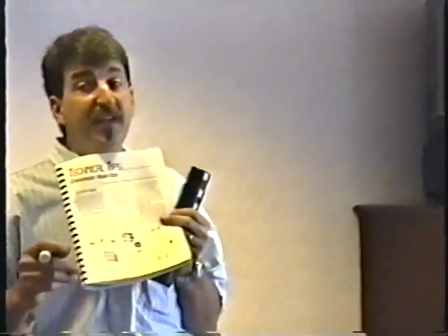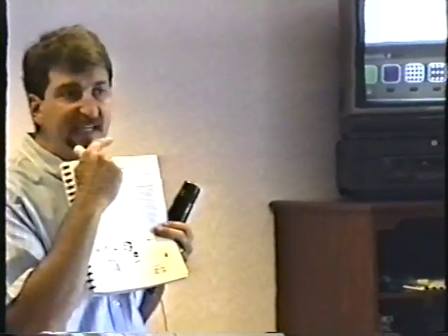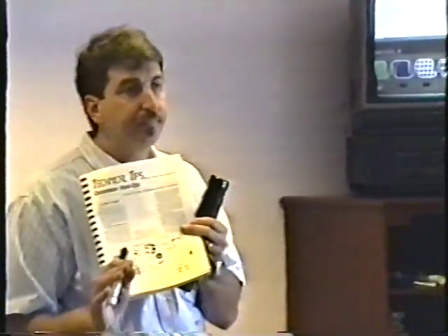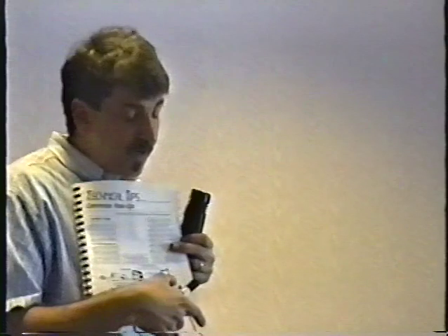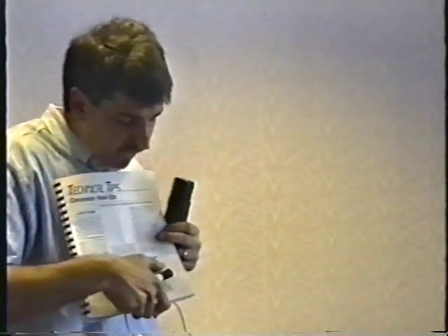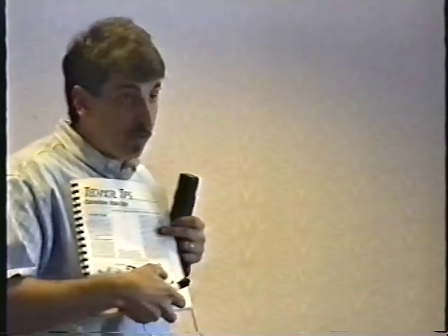And in fact, in the older games, the positive sync was separate syncs. Separate vertical and separate horizontal sync. They did not use composite sync. But the negative syncs are composite. And there's a separate little 3-pin connector that we use for negative sync. On the separate little 3-pin connector, pin 1 is ground.